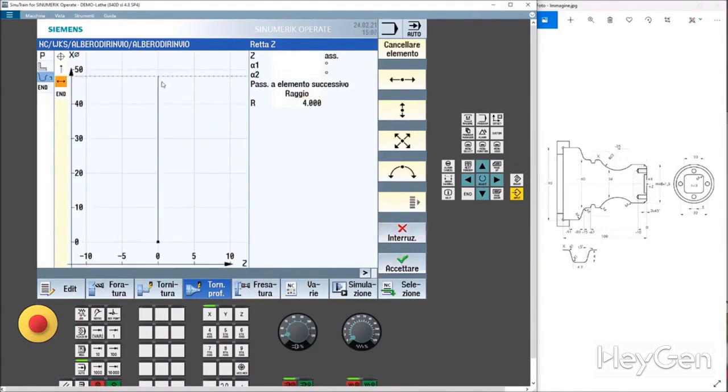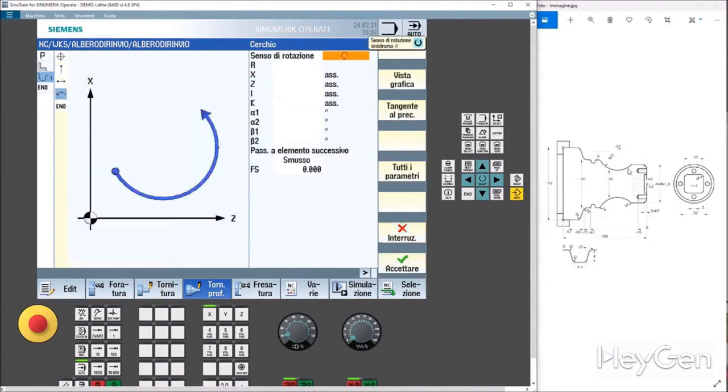Okay. A segment, a line without an end. Without direction, it's dashed because it tells me there's something wrong, something doesn't add up. Perfect. At this point, we need to do a circular interpolation. Here it is. The tool's direction of travel is clockwise. The radius of our interpolation is 23. The final x is known.